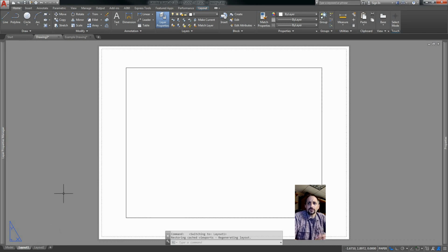While on the topic of paper, please note there are 5 common ANSI paper sizes primarily used. ANSI A, 8.5 inch by 11 inch, also called letter size. ANSI B, 11 inch by 17 inch, commonly called ledger size. ANSI C, 17 by 22. ANSI D, 22 by 34. And ANSI E, 34 inch by 44 inch. Note that with each size increase, the area of the paper doubles. So you could fit exactly 16 A size sheets within one ANSI E size sheet.